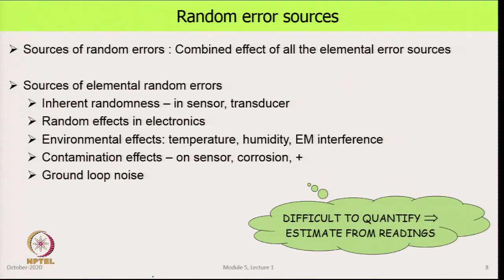So, we have two methods. Both of those methods gave us what we were looking for, which was S x bar I. We got that. Half the story of uncertainty in the measurement has been done. So, in the first technique that we saw, technique number 1, we only took readings, and based on the readings, which was the combined effect of all elemental error sources, we estimated S x I bar. In method 2 that we just saw,